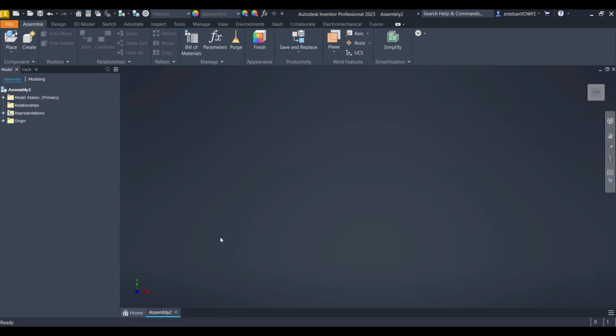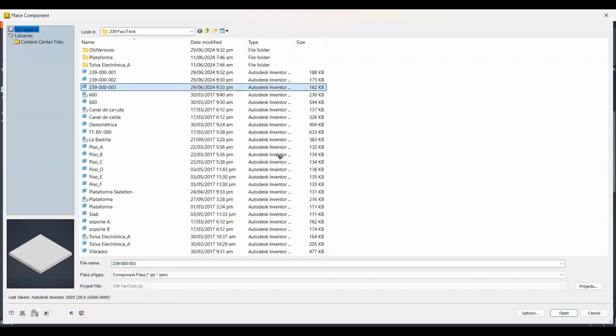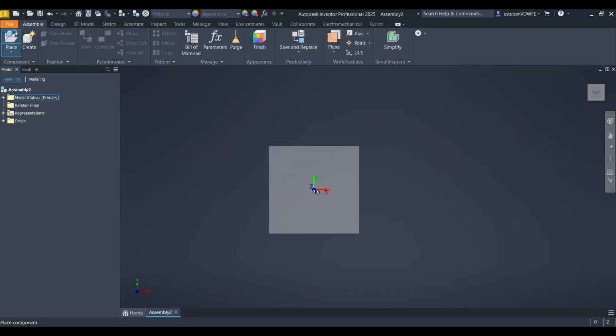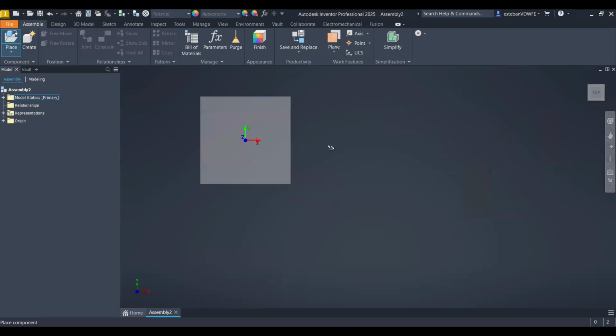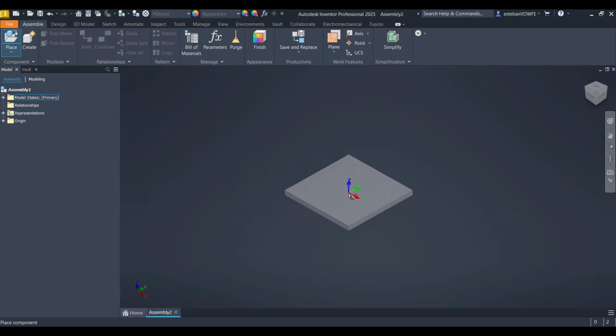Okay, so being here, there are some extremely basic things, like how to place a part. We have many options in here, maybe too many for this video, so I will cover just the placement. When we insert a part, as you saw, I just selected it from the folder, and it is waiting for a point where I can drop it, right? It's exactly the same as SolidWorks, where we just click on the check, and the first part goes to be assembled fixed at the origin.